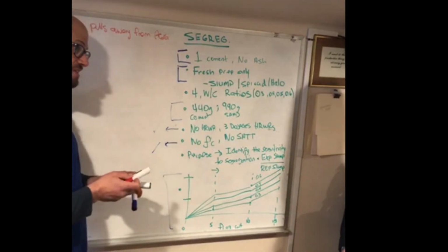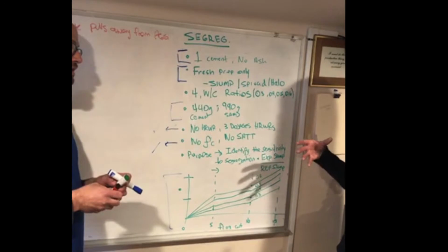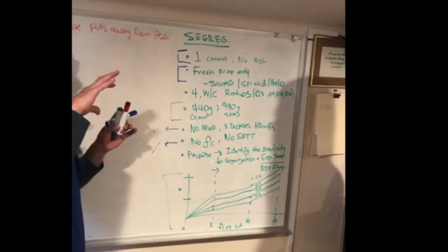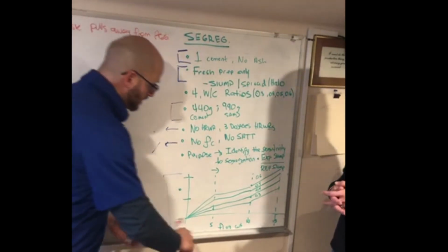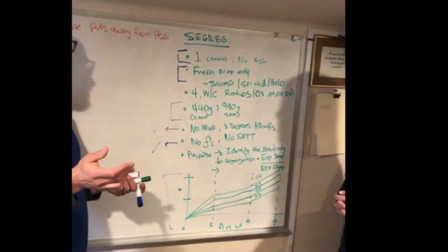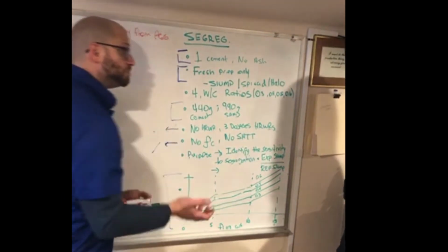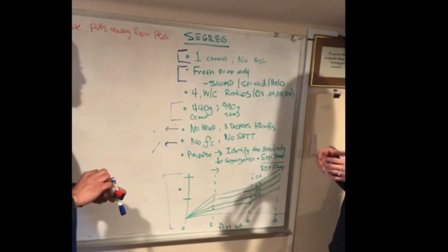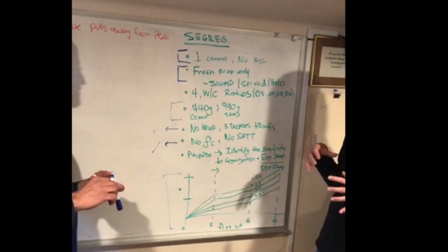Does that make sense? Yes, but how is that going to give us... Are we looking for the actual spread number? Yeah. And we're going to compare it to the reference at that water cementitious ratio, and then graphically show what that comparison is. Now, I don't know, this might not work. It looks like it should, but graphically we'll have to see it. So that number, will it really give us a moment when the segregation occurs?